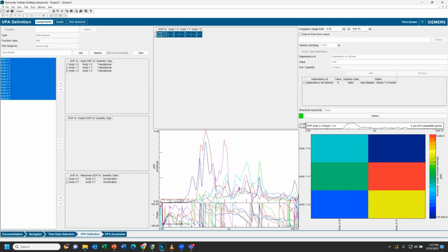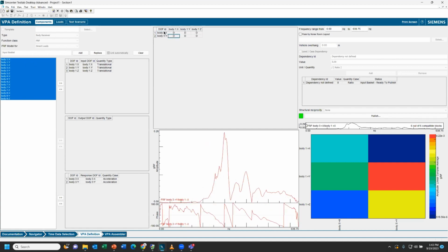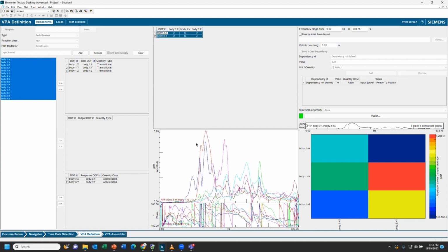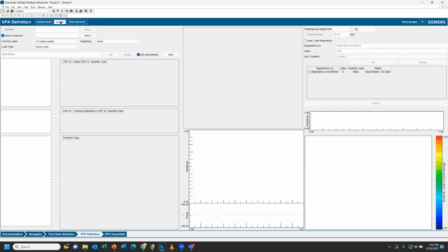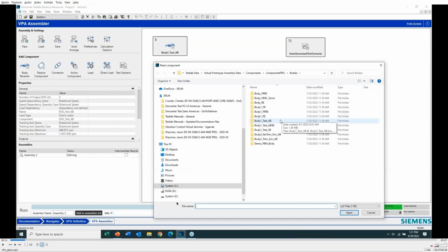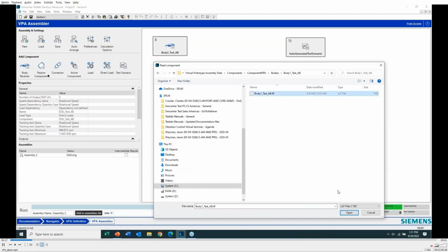With this, you can create different components. So for example, here I selected some FRFs of my structure, and I can save that as an assembly. And then same thing, I can create a source that's a set of loads that should be based on blocked forces, and create a component like that. What this lets you do, I'll play a quick movie here to save some time, is create a library of different parts of the structure.